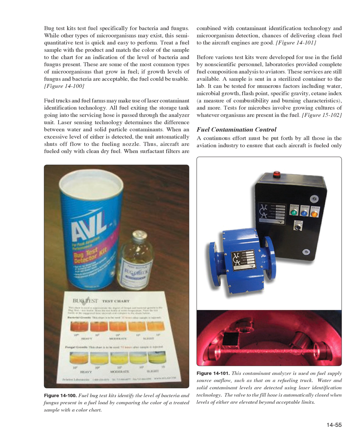A sample is sent in a sterilized container to the lab. It can be tested for numerous factors including water, microbial growth, flash point, specific gravity, cetane index, a measure of combustibility and burning characteristics, and more. Tests for microbes involve growing cultures of whatever organisms are present in the fuel.